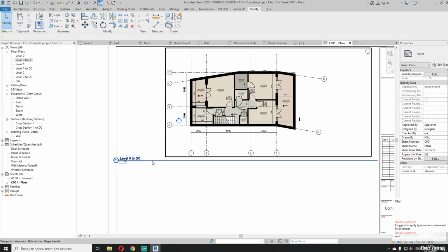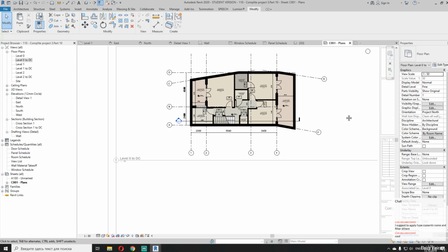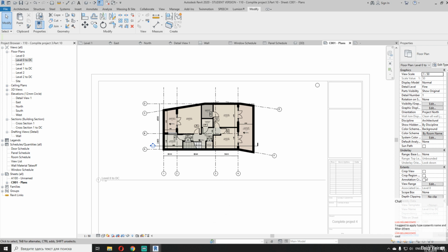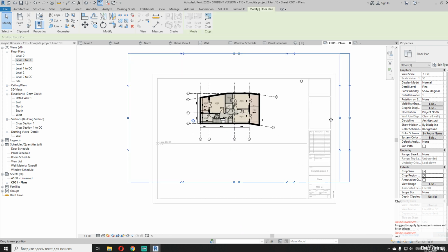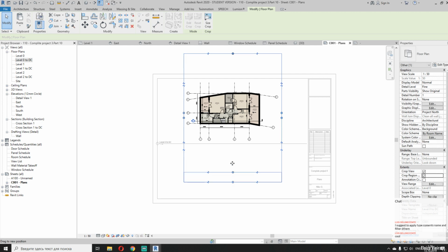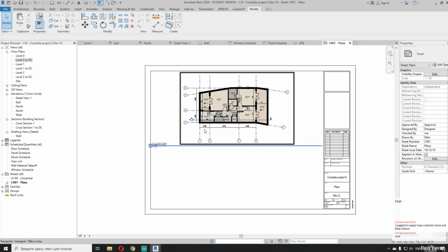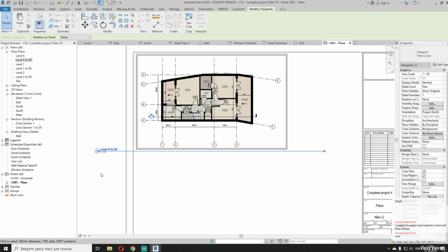And let's change these dimensions. Let's go inside of that. After that, I will use the crop view and view it. I want to see it with my cropping view. Yeah, it's here, and let's make it smaller, like this, and like this. Double click on that, and as you can see, my view is becoming smaller.